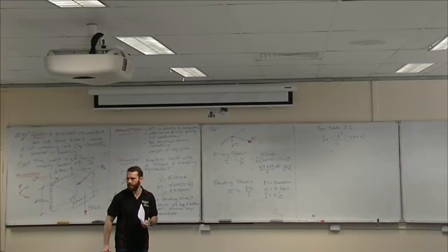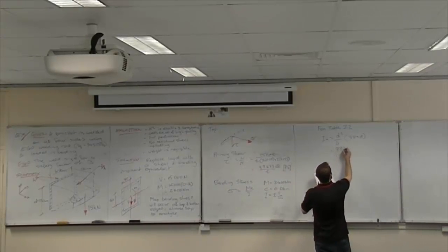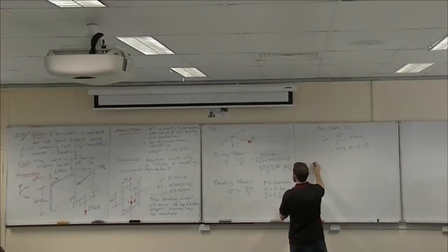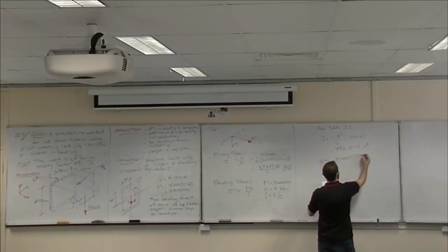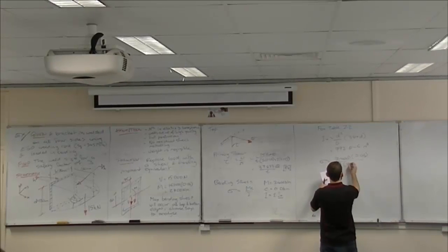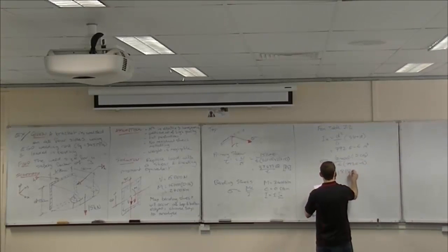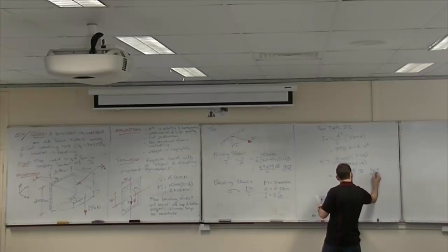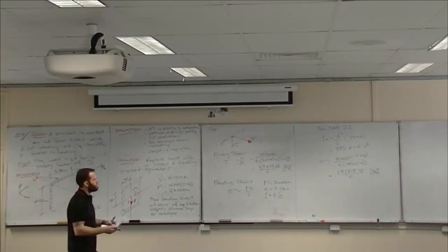Alright, anyone got an Iu yet? 792E-6 meters cubed. Very good. Alright, so that going in, sigma equals 2400 times 0.06 on t times 792E-6. And I get 18.18 on t in pascals. Are we good with that? Yep. Alright, what's the next step?